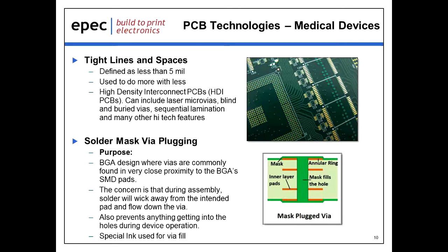And with these types of designs come other things like using laser microvias, blind and buried vias, sequential laminations, and many other high-tech features that typically go along with HDI. But there are some challenges with it, and we'll talk about that here in the next slide.